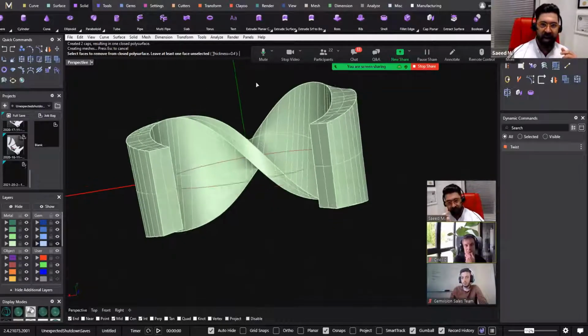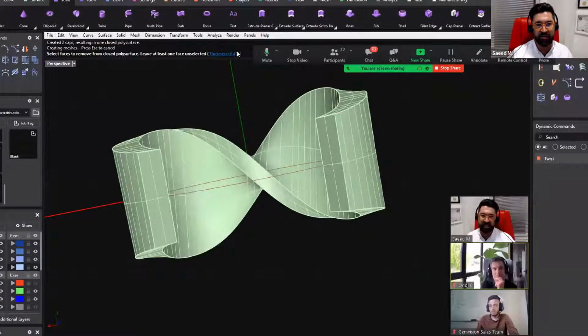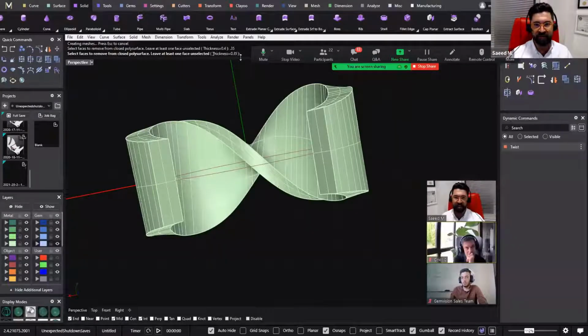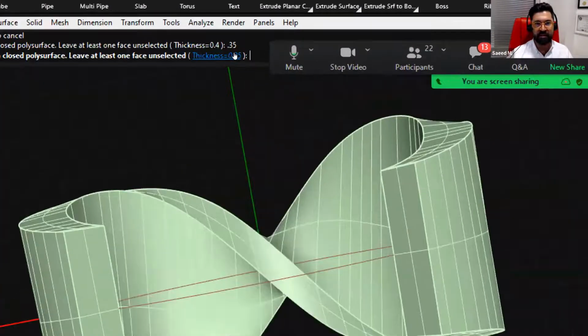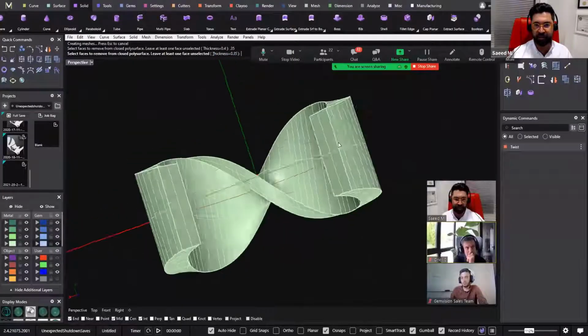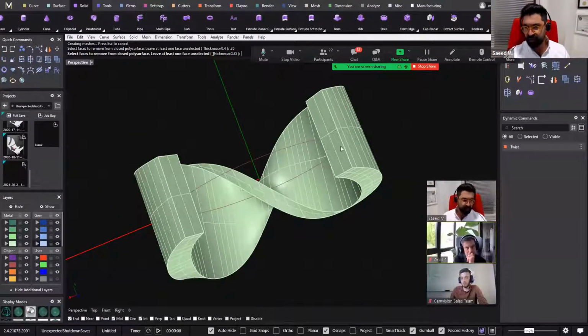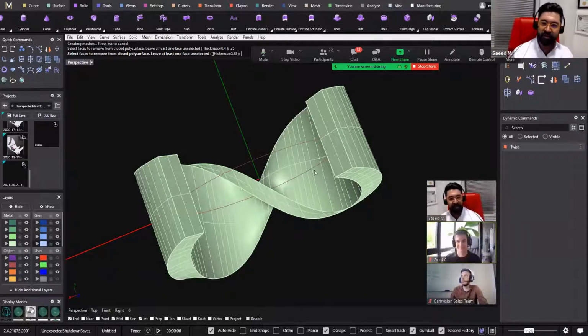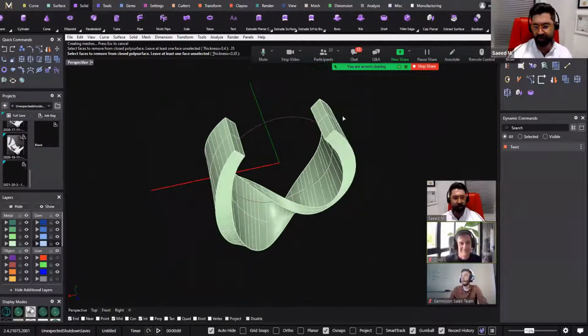Right now, I do 0.40, or even right now in the world, they use 0.35 mm for making a shell wall thickness because of the gold price. If you want 18K gold or 14K gold, right now in the Middle East and in Europe, because of the COVID-19 economic crisis, all the gold and jewelry manufacturers try to have a big shape with the minimum metal weight. And it's very important to have the minimum metal weight.